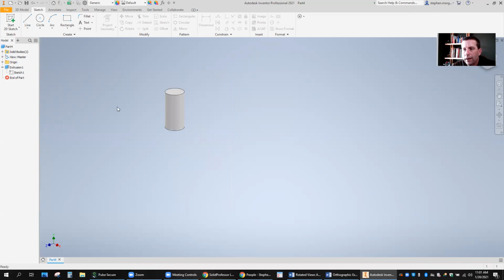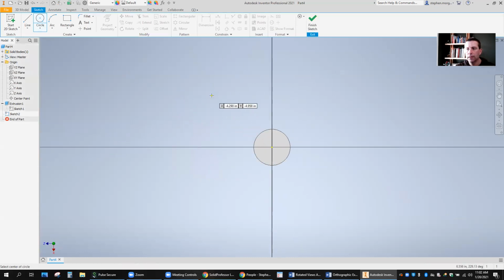All right. Then we're going to repeat this workflow over again. So we're going to go back to the Sketch tab. We're going to select the circle again. And now it wants to know what plane or what surface do you want to sketch on. So if I expand this, I could select the same planes that were available to me in the beginning, or I can select this top surface of the part. I'm going to select the top surface.